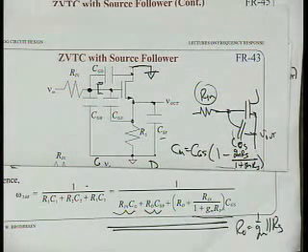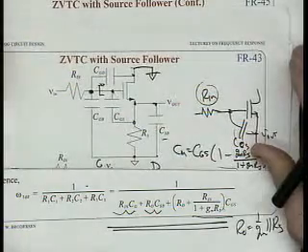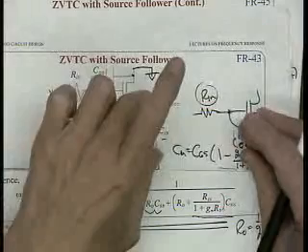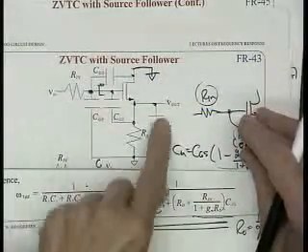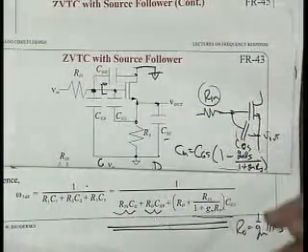It can work for a very complex circuit. I think the real insight to get from this is this idea of time constants. The idea that you have a capacitor, you find the resistance driving that capacitor, and that is a part of what sets the dominant pole.